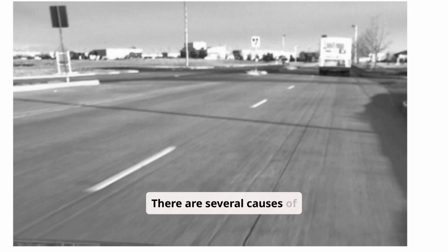There are several causes of mat tearing depending upon the type of mat tearing or streaking. Some major causes are listed below. Warped or worn screed plates have an increased likelihood of dragging aggregate particles along the mat surface due to larger friction and have more potential defects that can grab aggregates. A screed plate tends to tear the mat at the beginning of paving operations if it is not preheated. As the hot asphalt heats the screed, this type of tearing will generally disappear.